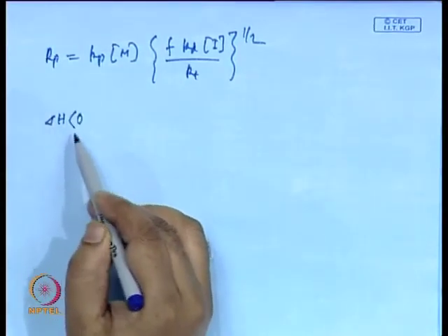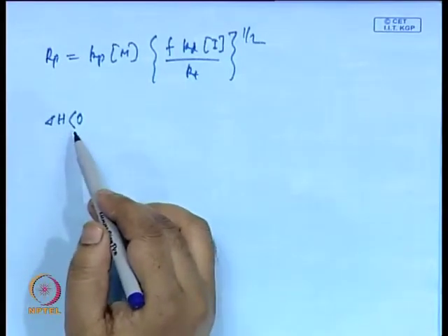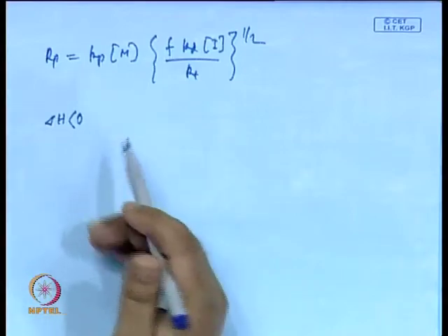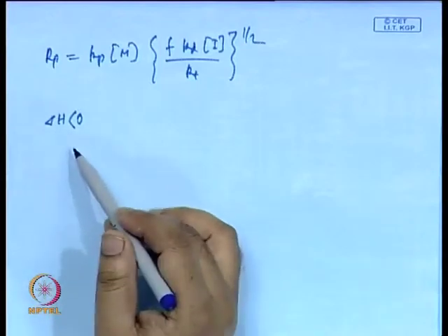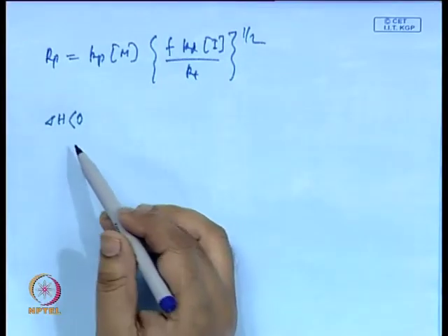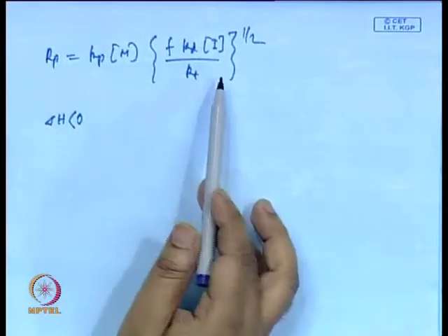What we did not consider is that during polymer reaction we know that it is an exothermic reaction. Now, once the exothermic reaction happens, if we do not have arrangements to take out the heat which is evolved during the reaction, then there will be a change in temperature. If we cannot take out that heat quite effectively, then the temperature will rise, and once the temperature rises, all these rate constants will also vary. So, the rate of polymerization also varies if we cannot take out the heat which is generated due to the polymerization reaction, which we did not consider in deducing this steady state kinetics.